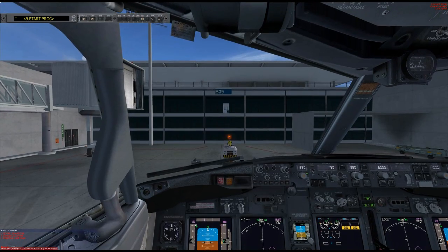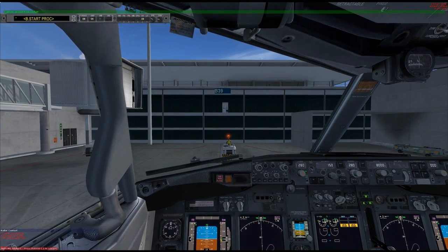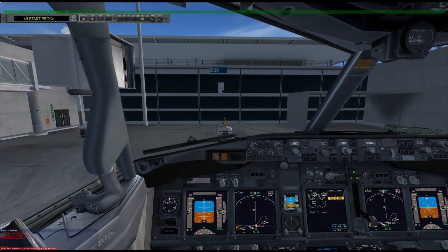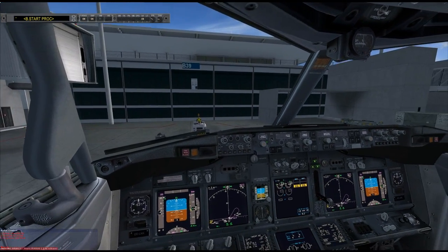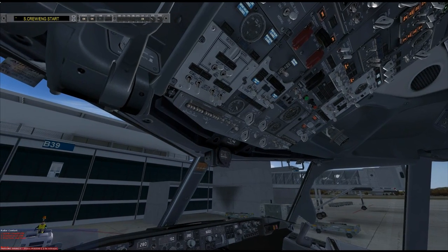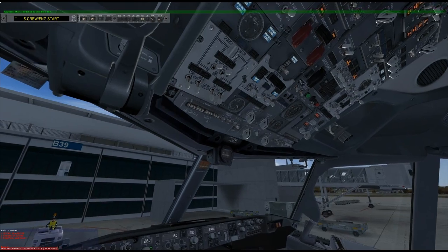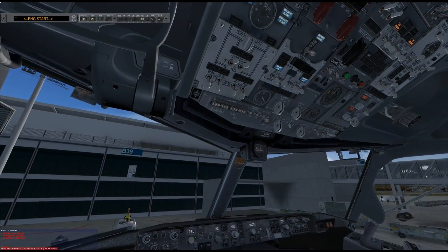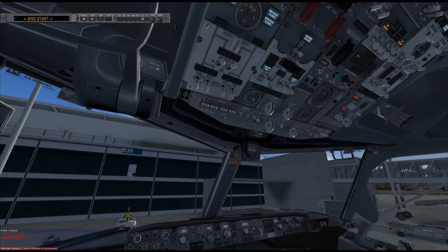Ground from cockpit. Go ahead. We are ready for an external air engine start. Your walk around is complete and all doors and hatches are closed. You're clear to start engine number 1. Start sequence 1, then 2. Check. Starting engine number 1.